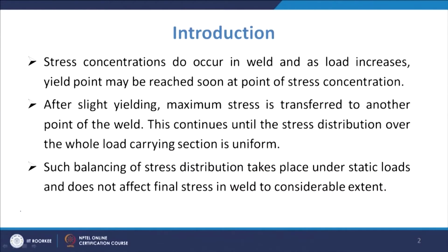This way it will continue until the stress distribution over the whole load carrying section is uniform. Such balancing of the stress concentration takes place under the static loading cases, and for the purpose of the stress calculations, they do not affect the final stress values in the weld to a great extent.